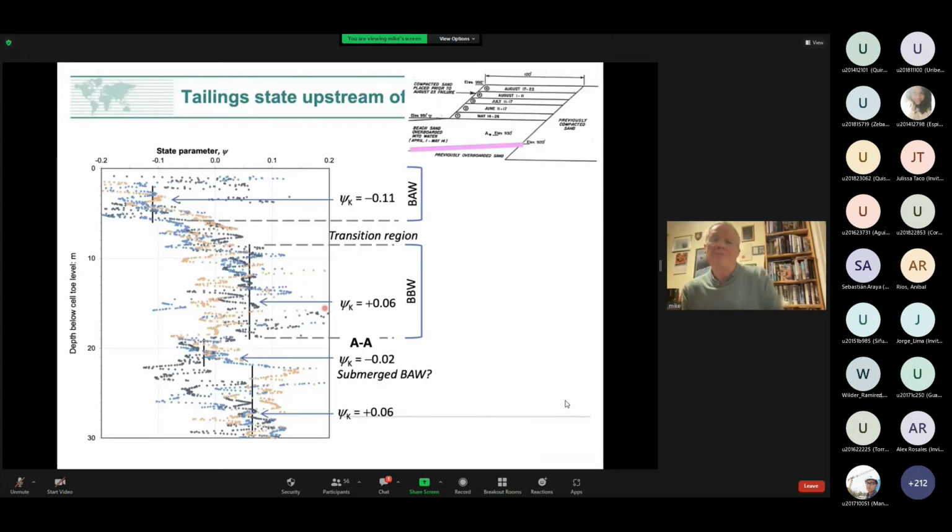So we go back to my Tower Island case. Here is our process CPT data. And these lines on here are now the engineering judgment of what is characteristic. Now you could go and start doing statistical games and try and work out formally what percentiles were and plot them up. But in all honesty, I prefer to do it by eye, because the eye is not so bad once you're looking in. And this was the characterization we came up with.